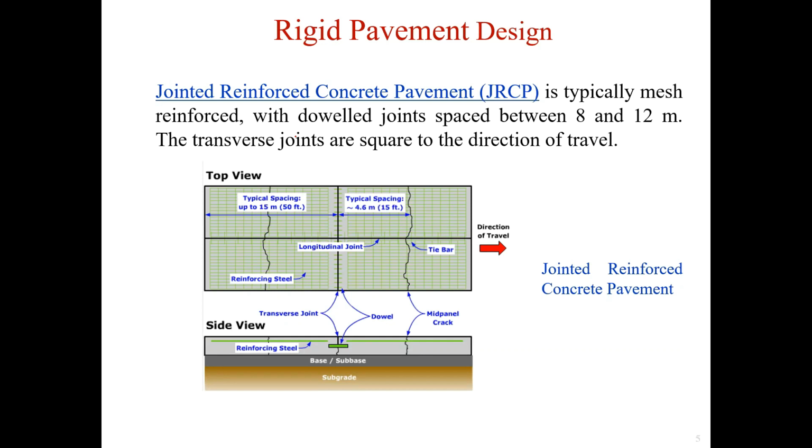In JRCP, the purpose of reinforcing steel or reinforcing mesh is not to prevent cracking of the concrete, but to hold tightly closed any cracks that occur in such a manner that the load capacity of the base is preserved. If suitable reinforcement is provided in a slab of acceptable proportions, cracks should not require any treatment during the pavement design life.